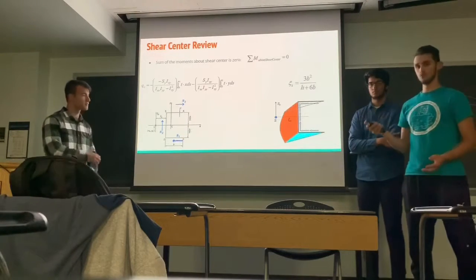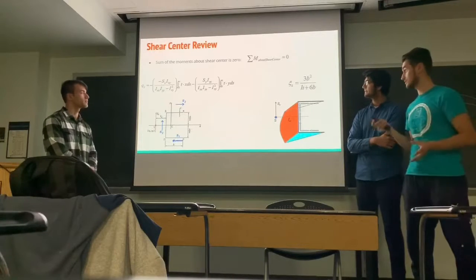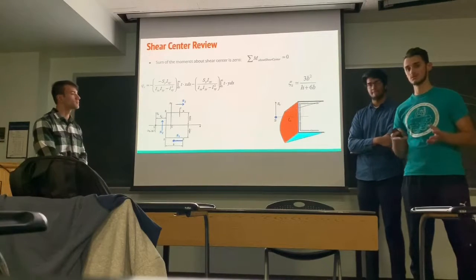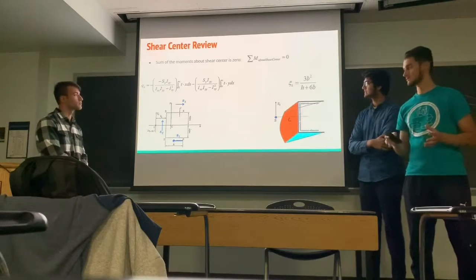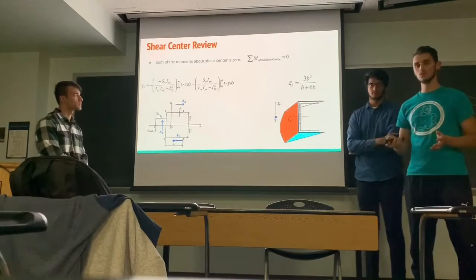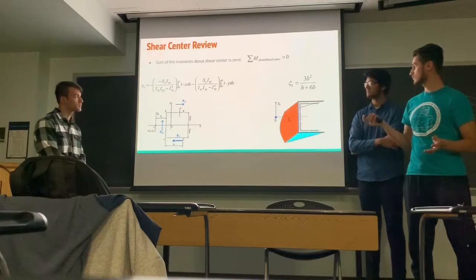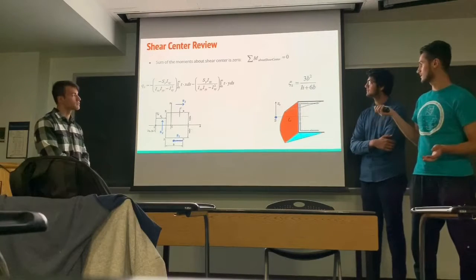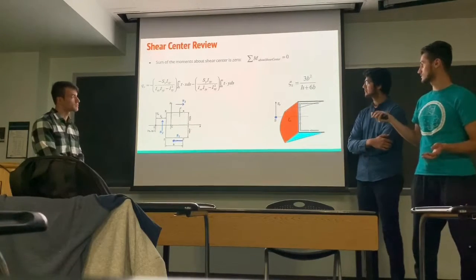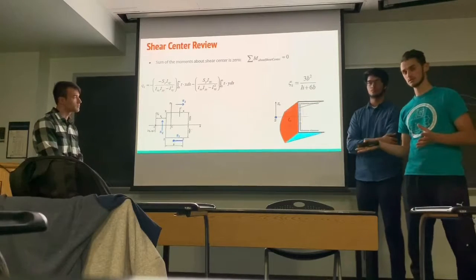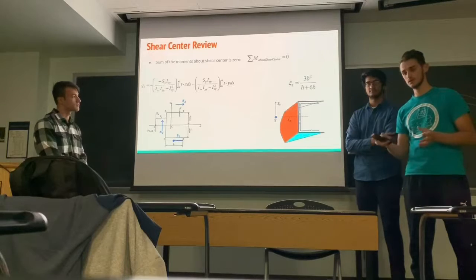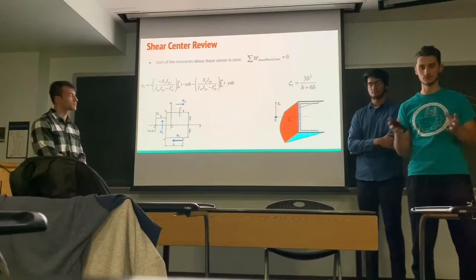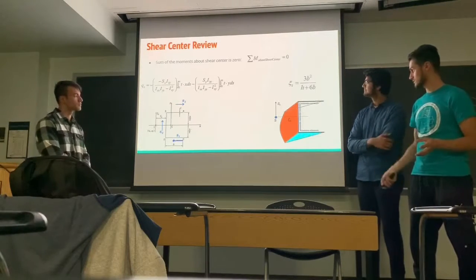Now, when we have this, we can finally move on to getting our shear center. An assumption for the shear center is that we have 0 moments about the shear center, so then we can basically formulate a solution in the form of this, which basically explains how to get the shear center location and takes into account shear loads and the torsional effects on the cross section.